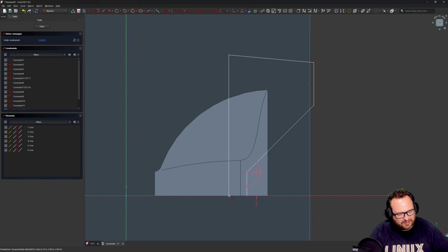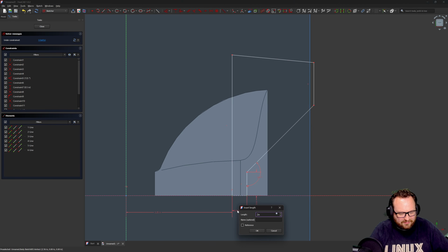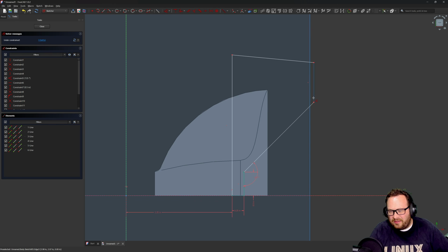And we're going to say D for dimension. And we'll give this a distance of something like 2.25 off of our center. And then we'll give this a dimension of 0.25. And then from here to here, we'll give this 0.625. So it's a pretty good size hole, right? You can get a tool over a lug nut, hopefully. I don't exactly recall the exact dimensions that it's supposed to be, but I think this is a reasonable estimate. We'll give this a distance of 3, right?